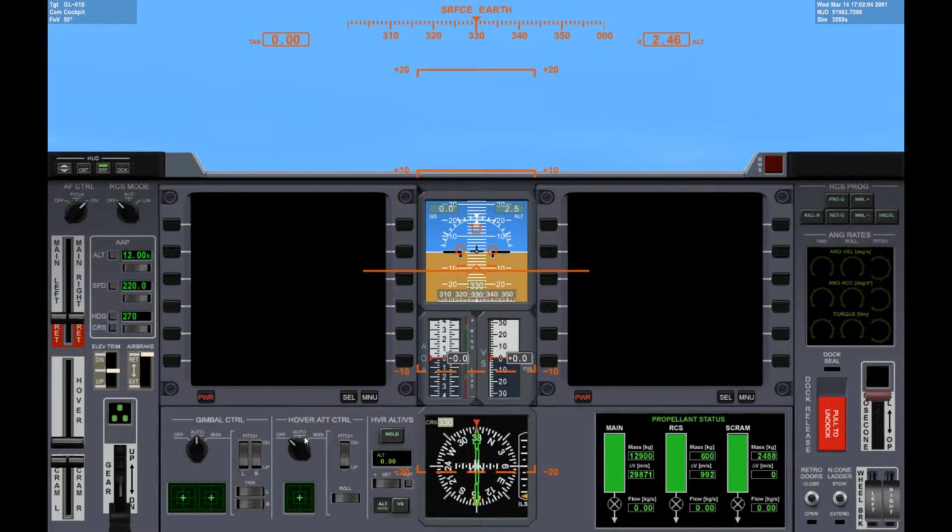Okay. You can do the same with the hover engines. This is kind of new. Here's some hover autopilots. If you do hover hold, then you'll basically hover as if you defy gravity, essentially neither up nor down. You can also set an altitude to hold at, which is kind of handy. You can also set a vertical speed that you can use to land and such.